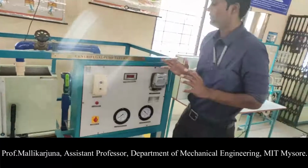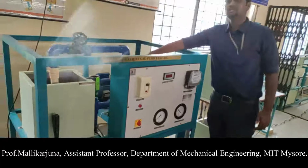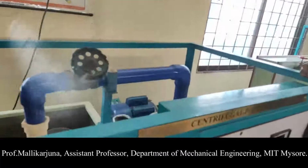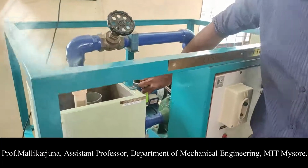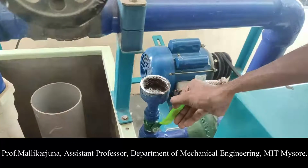So now if you want to conduct the experiment, we need to make sure that initially the suction pipeline is filled with the water. Then we need to switch on the mains from either side. So now I am conducting the experiment. Before that, I need to close this valve. Now this pipeline is filled with the water, and I am closing this valve.